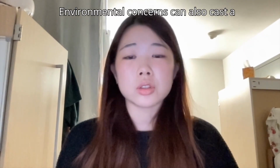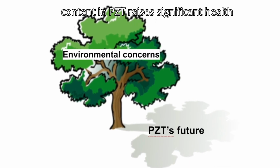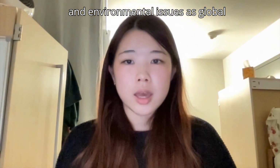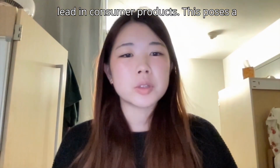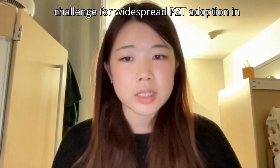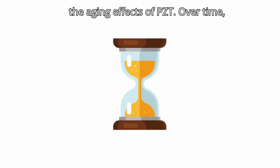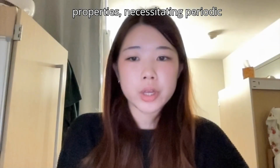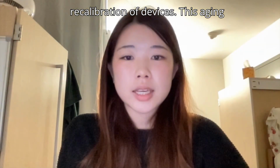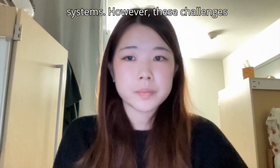Environmental concerns can also cast a shadow over PZT's future. The lead content in PZT raises significant health and environmental issues. As global regulations tighten around the use of lead in consumer products, this poses a challenge for widespread PZT adoption in certain sectors. Lastly, we must consider the aging effects of PZT. Over time, there's a gradual change in its properties, necessitating periodic recalibration of devices. This aging process can affect the long-term reliability and accuracy of PZT-based systems.